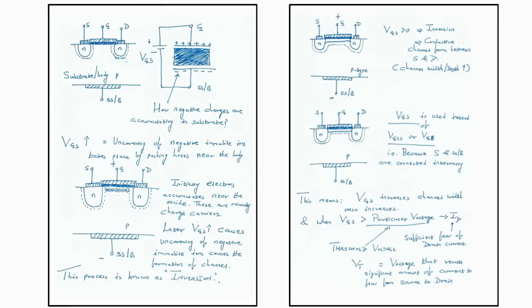If you see this particular schematic, what does it show? It shows that you have a substrate, and the type of wafer is p type. In that you have diffused n channel source and drain, and then you have a gate separated by a thin layer of oxide, and the gate is a metal. So, the contact is a metal.